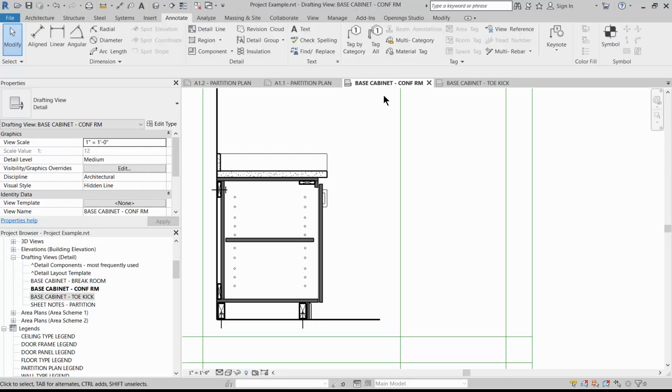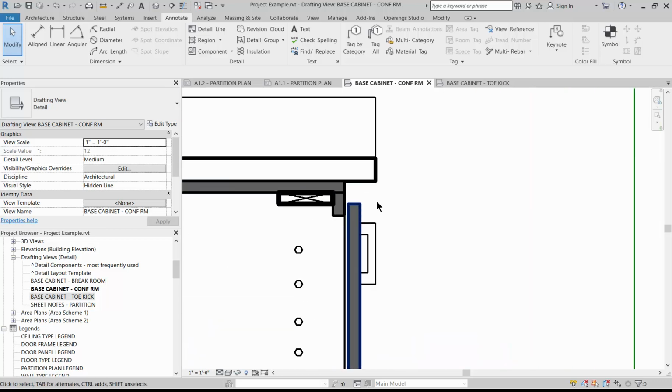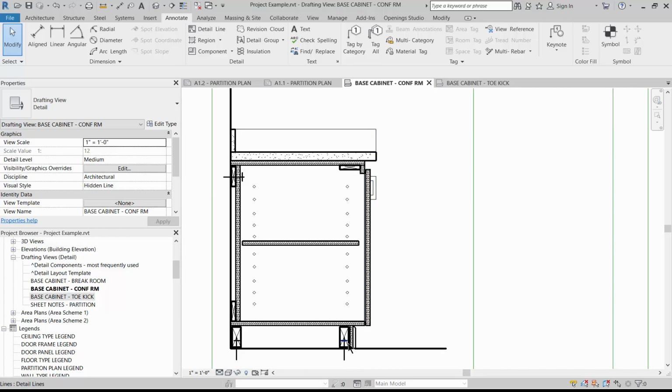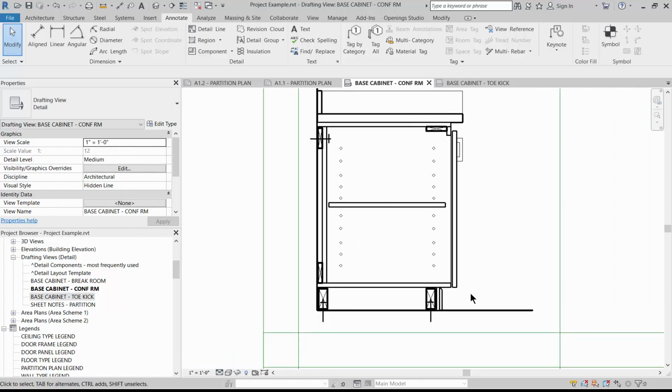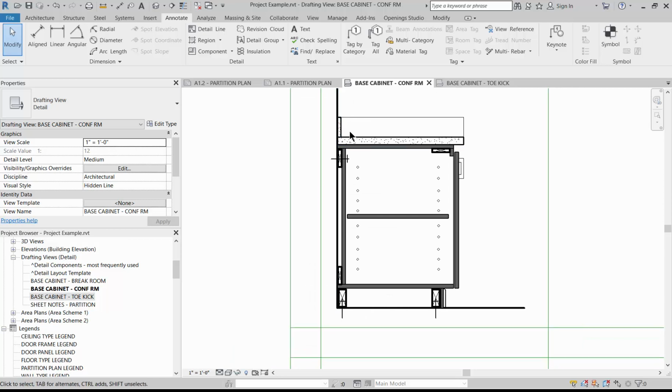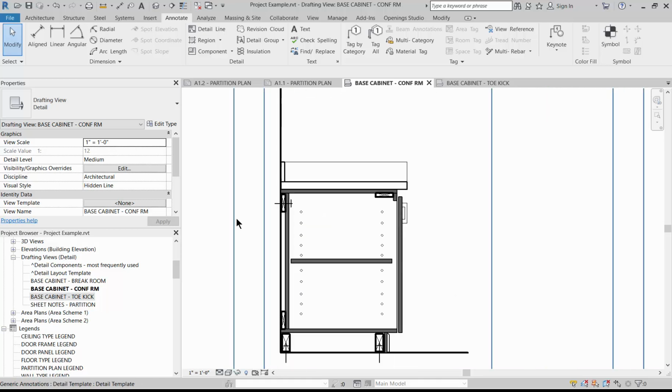In this step, we're going to take our previously drawn detail and cross-reference additional details, annotate it with notes, and look at how to place it on the sheet. So in order to cross-reference detail, you need to create enlargements of the portions of it first. So things we usually enlarge is the detail of the countertop, so you can show exactly the details and the distances here and the mounting of the handle, and then you might look at more detail of the base and how additional base is applied and what the transitions are, and even the back of the counter, so the backsplash.